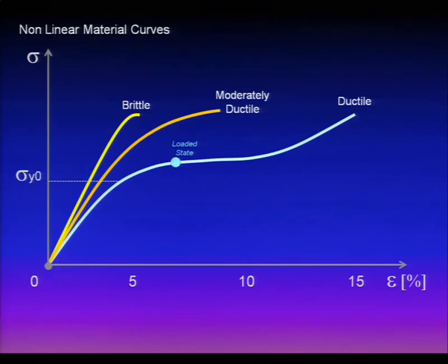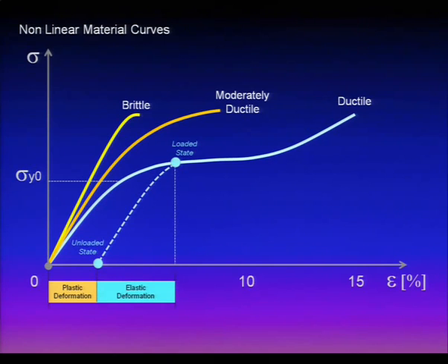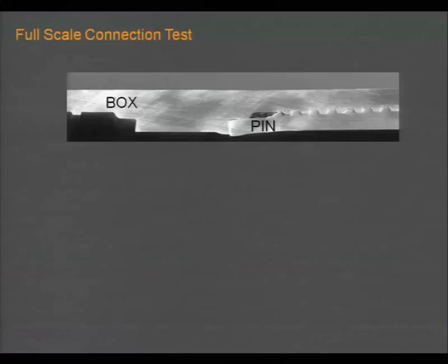Permanent deformation, plastic deformation. So if I unload this point, I get plastic deformation. Permanent deformation is the same; this is the name in SolidWorks Simulation. The rest of the deformation is elastic deformation, the recoverable deformation, and this is the total deformation, right? These are the three plots that I can get from SolidWorks Simulation.